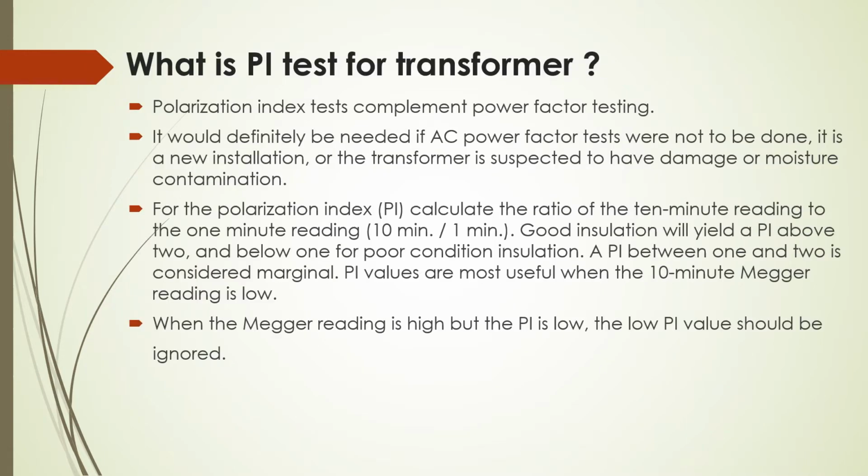So friends, let us see the typical questions asked on transformer testing. So what is PI test for the transformer? Polarization index test or PI test complements power factor testing. It would definitely be needed if AC power factor test were not to be done. It is a new installation, or transformer is suspected to have damage or moisture contamination.